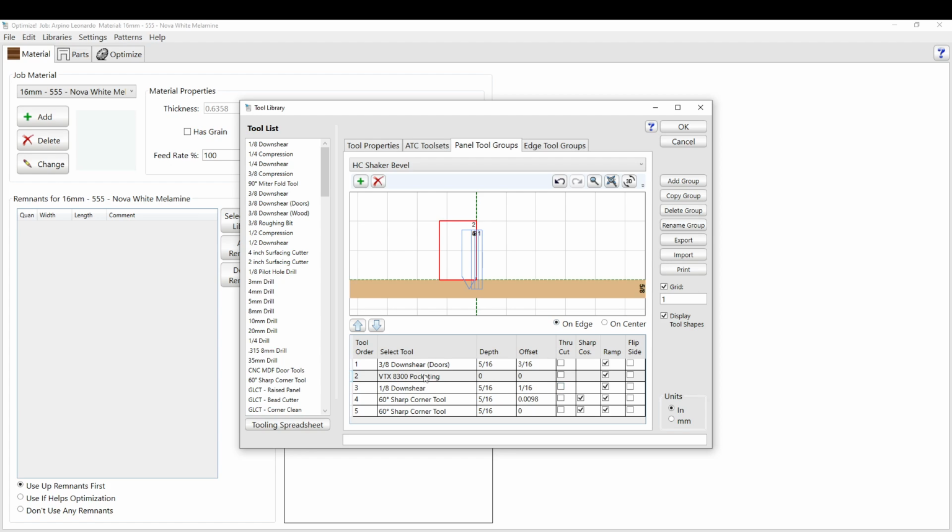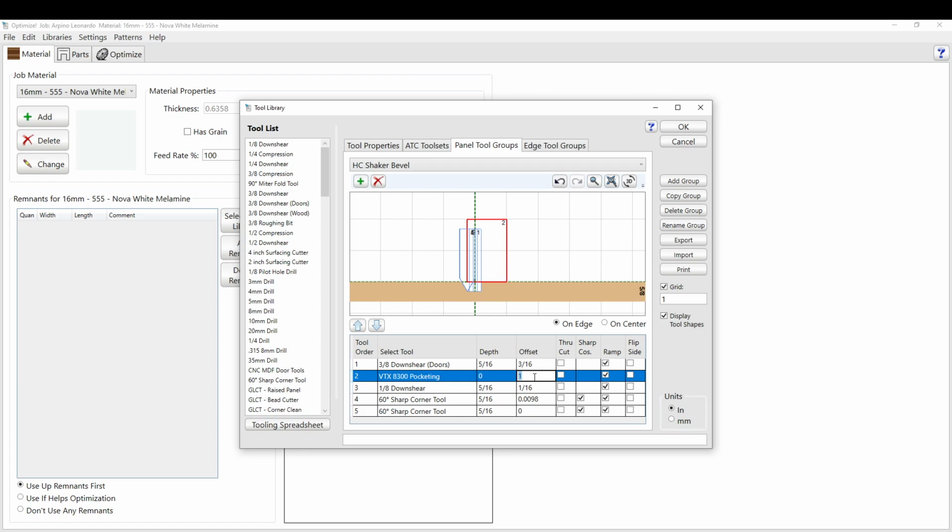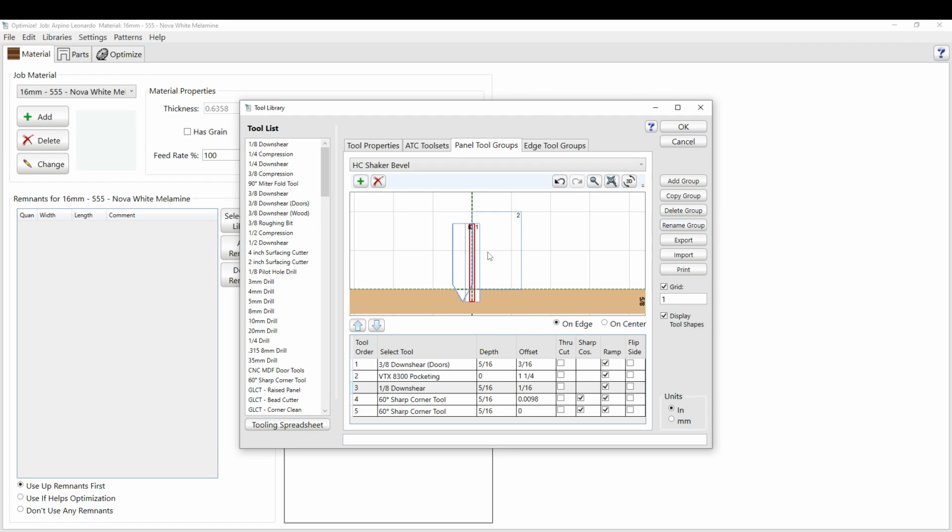And then you're going to offset it however you want. So I know this is a 2-inch bit. This is not the one I'm going to use. You don't want a pocket on this. Let's offset it 1 inch. Oh, it must be bigger than, oh yes, that one's like 1.5. No, 1.25. So that's how you get it to where you want it to be exactly.